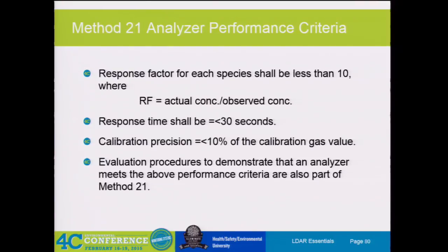It's going to be the smaller blips that I would want to look at. Because instead of a high end like propane, where you have a very quick response, when you're talking about your back ends, like your crude units, it's going to take longer for the TVA to react. So you want to make sure that you're sitting there and actually letting the machine do what it needs to do. So talk with a technician and let them understand the process. They don't need to understand it from an engineering side, but here's heavy end units. Spend a little bit more time. The smaller blips you want to spend more time on.